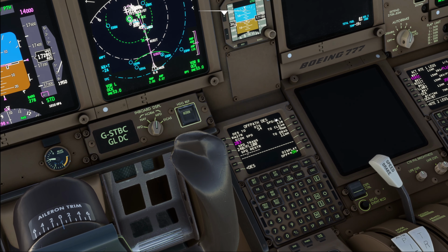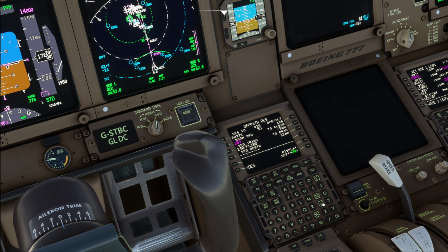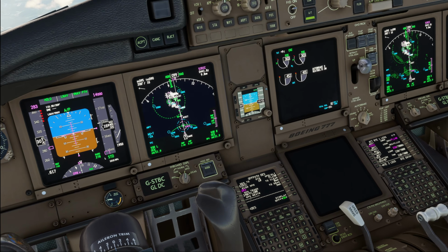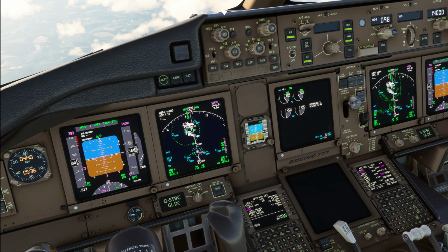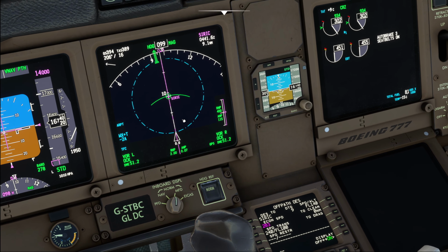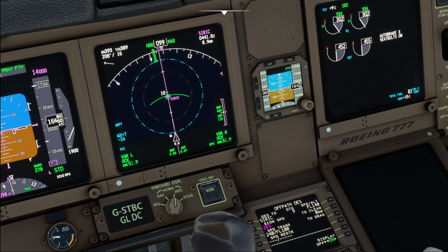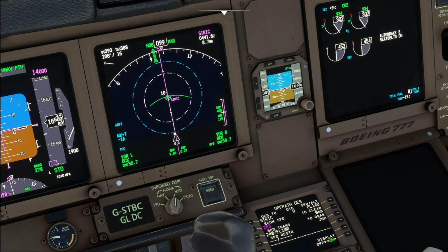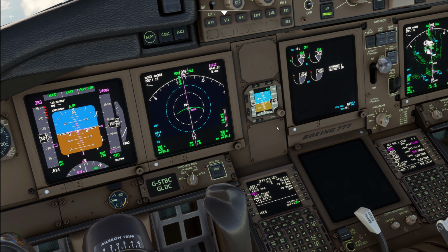Let's have a look at an example. If we enter Zurich in there, like this, it automatically takes over the restriction from the flight plan, and you can see that now it's calculated our descent rings here again, and you can see that we're exactly on the blue ring. So we are exactly on the clean path profile to this waypoint and this altitude.